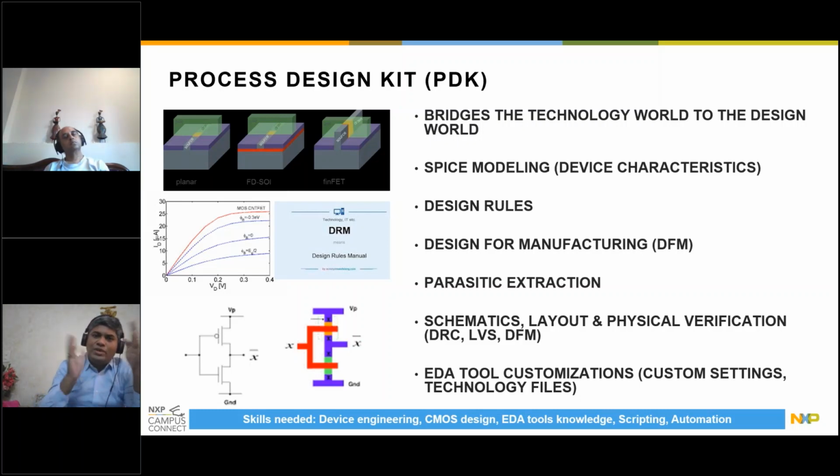So what we intend and what we get may be different, right? Because you have designed something on paper. For example, you have scribbled the circuit on paper, then you have laid it out. When you laid it out, there are a lot of parasitics which come, whether it is capacitances and interferences between various layers on the device, etc. Now these have to be also modeled, because eventually these parasitics, that's why we call the word parasitic, have to be known. If they're unknown, then we will get something else on silicon unless we are anticipating those at the CAD stages. So parasitic extraction helps you to anticipate end effects because they are fabricated on the chip in a certain way. So those models are also part of the PDK domain.